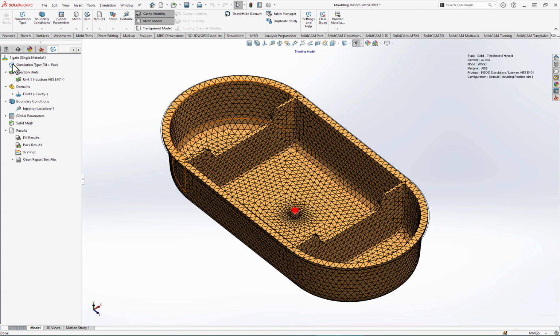So I've already said, let's assume that we saw a troubling result of some description there, and we read the advice there, and one of the things that it advised that we try is maybe editing the current wall thickness that our part has been designed with. So this part in particular was designed with a 1.8 millimeter outside wall. So I'm going to vary that thickness to 2.2 millimeters thick. So here's how I would do that.